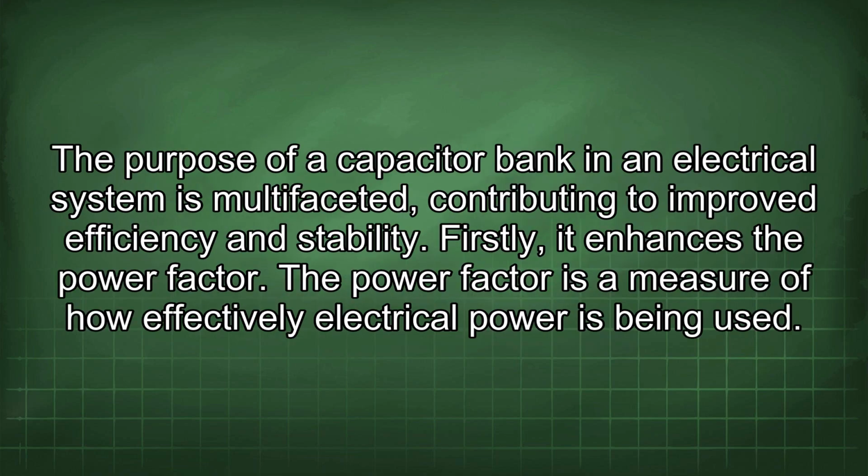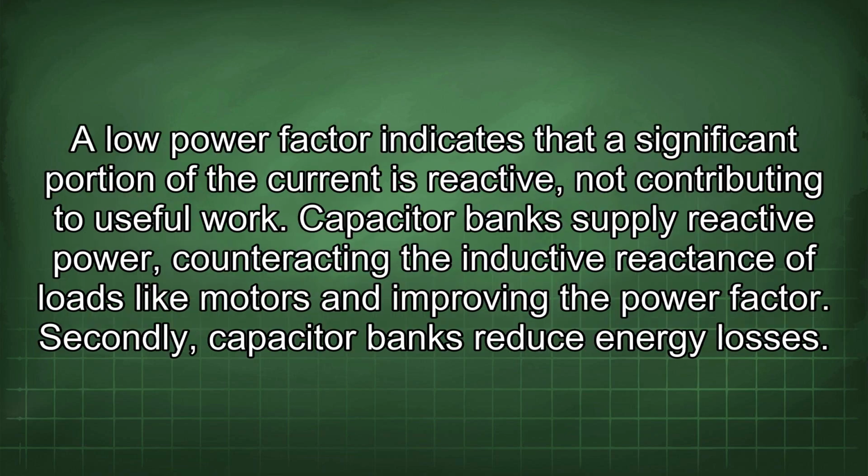The purpose of a capacitor bank in an electrical system is multifaceted, contributing to improved efficiency and stability. Firstly, it enhances the power factor. The power factor is a measure of how effectively electrical power is being used. A low power factor indicates that a significant portion of the current is reactive, not contributing to useful work. Capacitor banks supply reactive power, counteracting the inductive reactance of loads like motors and improving the power factor.